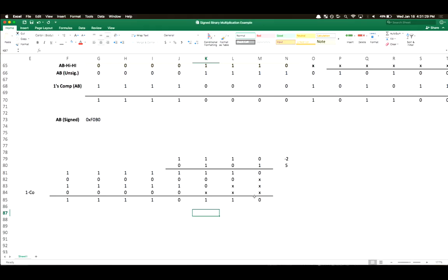Do we manually put that on the register? No, so you're gonna have a carry in and carry out of your ALU, and that carry out is gonna feed into like a 1-bit register and just stay there, and then you can have it clear on every clock cycle at the end of it. That's up to you of how you want your overflow register to act. It can stay there, or you can have an instruction to clear it. That's totally up to you.